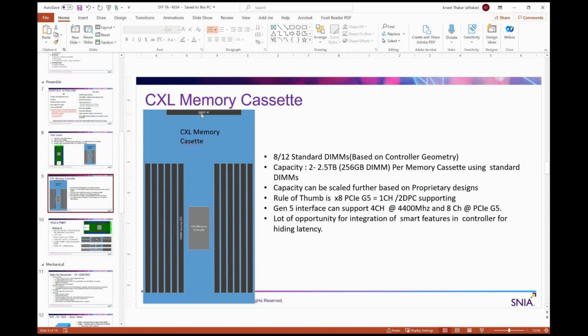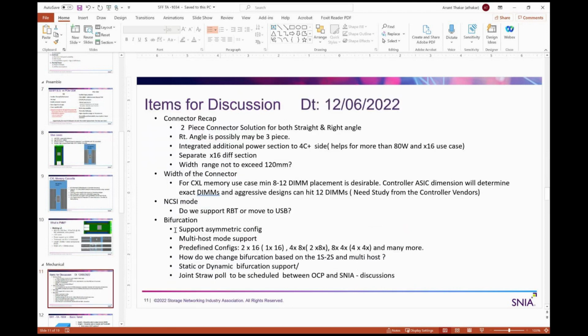Anand, if you can think of having, say, another 4 outward-facing CXL ports on this, then we can connect it to multiple hosts. I haven't gone into much detail on this one, but there is a bifurcation effort of the by 32. I could partition it into 2 by 16, 4 by 8, or 8 by 4, or I could do combinations of that.